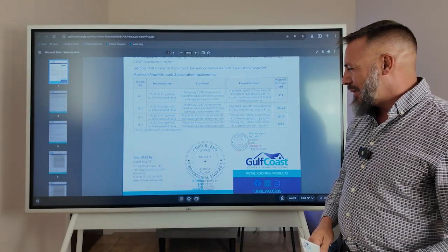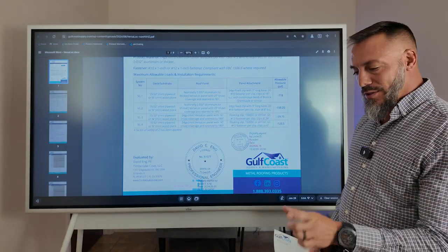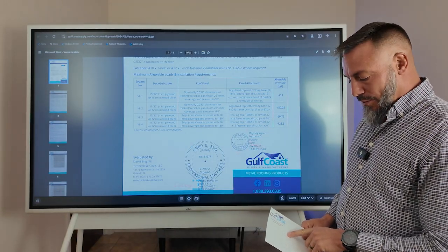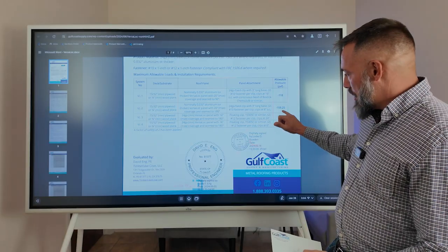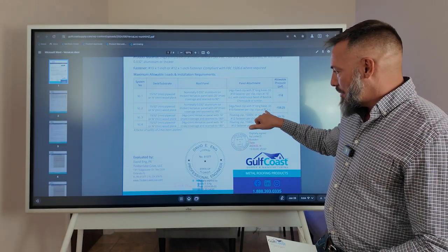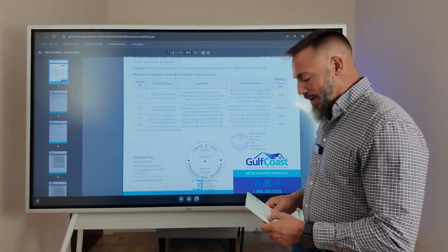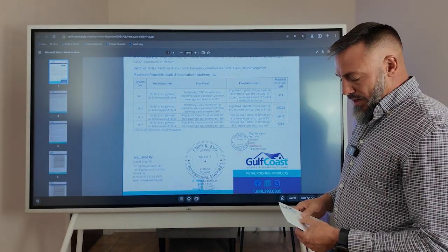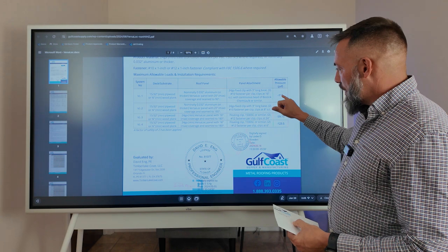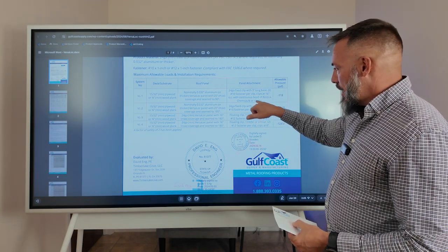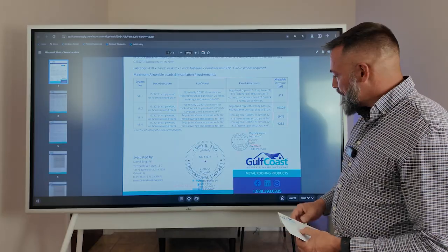I could also probably go down to 3 inches if I had to, which means the clips would be touching in that zone 3. I would open them up because I need 142.4 in zone 2. So 142.4, I could get away with 8-inch clip spacing, 24 gauge, this VL2 fastener pattern here. And then in zone 1, I need 107.8. So I could get away with 16-inch clip spacing and then a continuous bead of sealant in that.